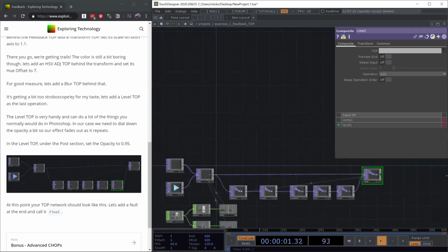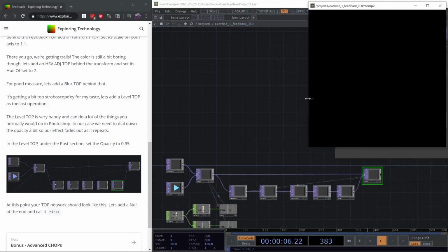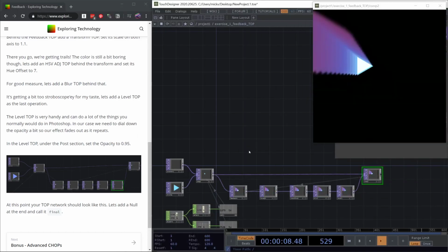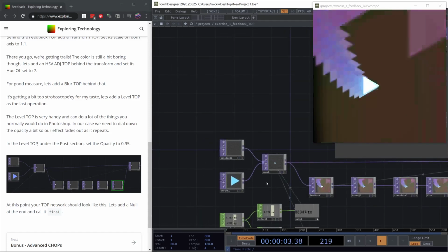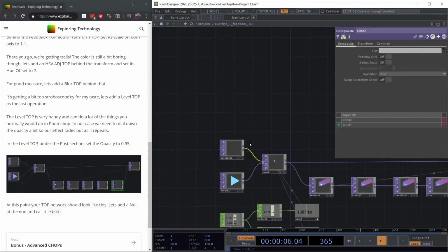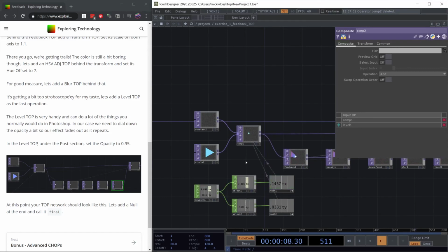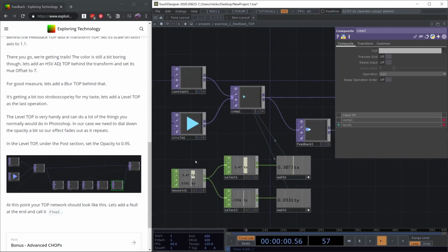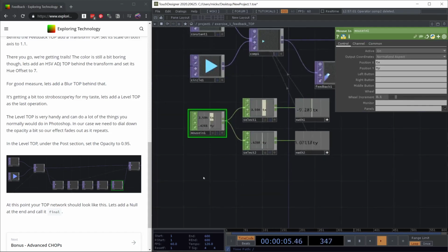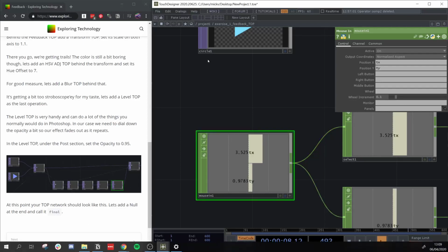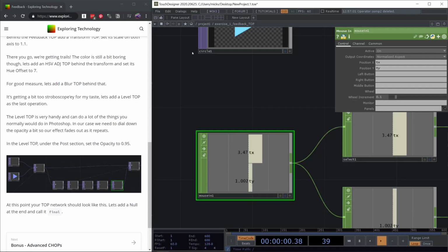Now, just to briefly talk once more about the jumpy rainbow example. We've had some people that are still struggling with getting the mouse to react with the position of the triangle. So I'm going to briefly recap what's happening here. We have our mouse in CHOP, and it gives these two values that are currently not yet the correct values that we want, because we want both of those to be between -0.5 and +0.5.